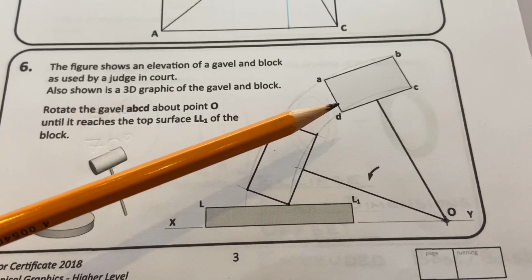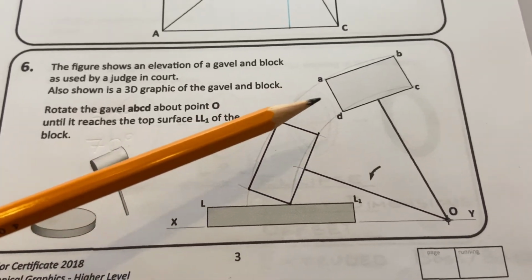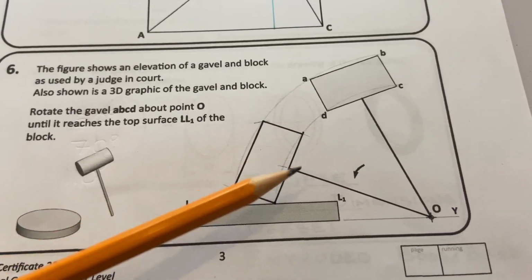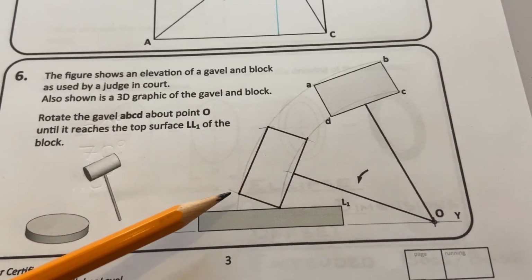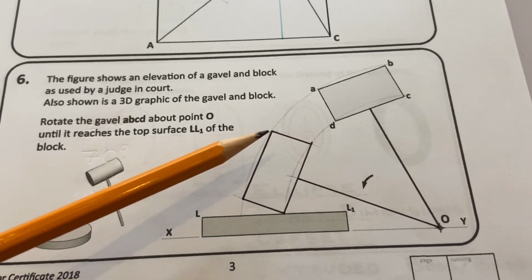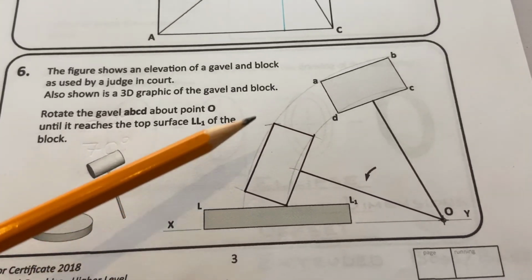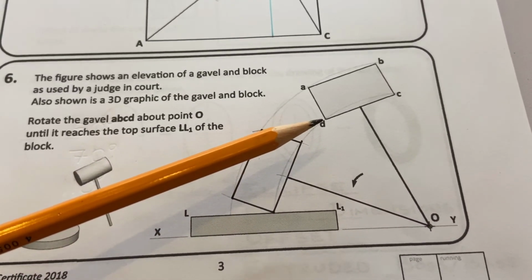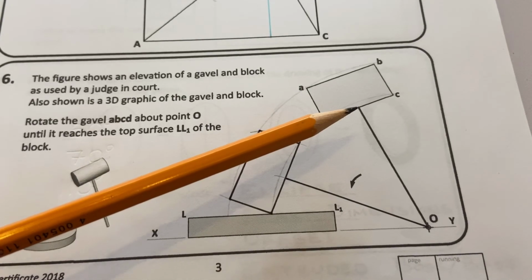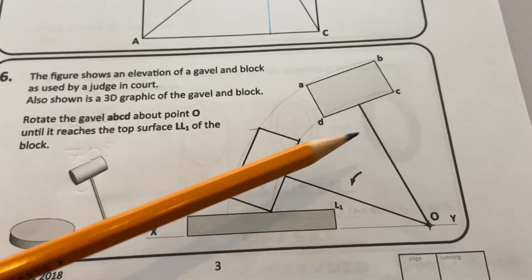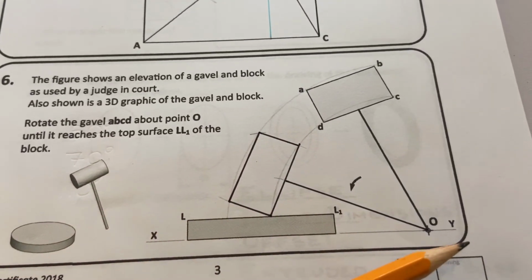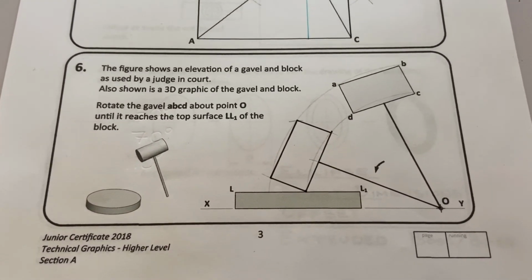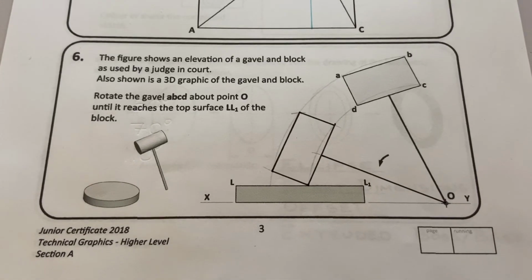Now, the line AD is coming off that at an angle of 90 degrees. So once you have this line established at 90 degrees, bring a line out here at 90 degrees until it cuts this arc, and then we can heavy in this block here. And then finally, put your compass on D, take the distance to that point there, the halfway point, mark that there and join it back to O, and that completes that drawing. So that's question 6, rotations.